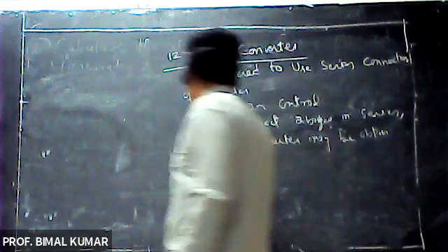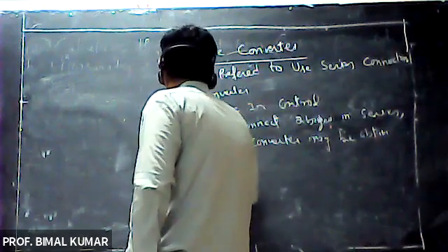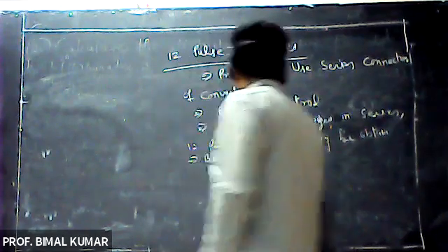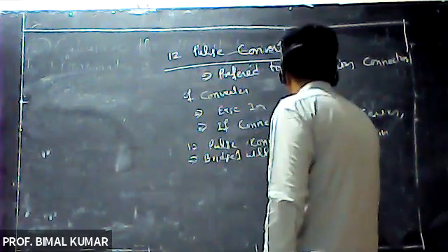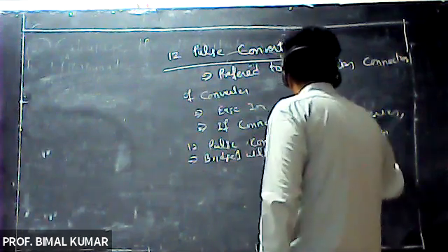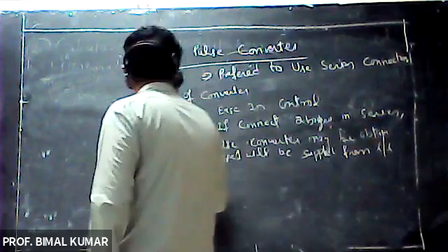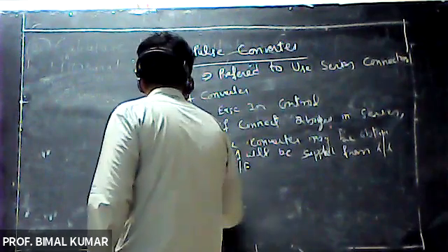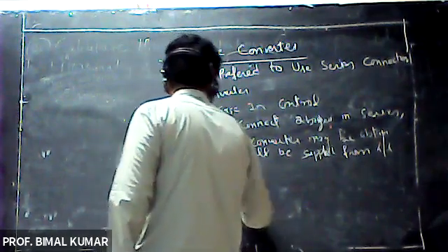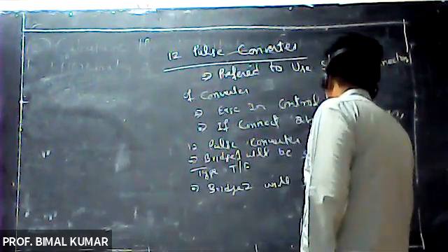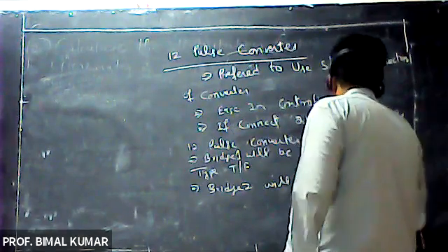Bridge 1 will be supplied from star star type transformer, and bridge 2 will be supplied from star delta type transformer.